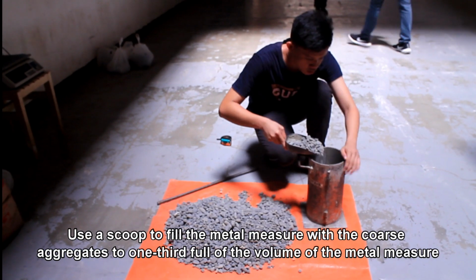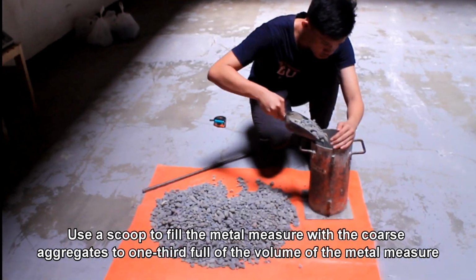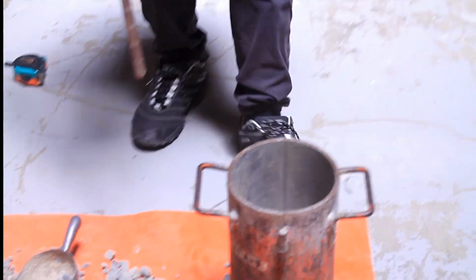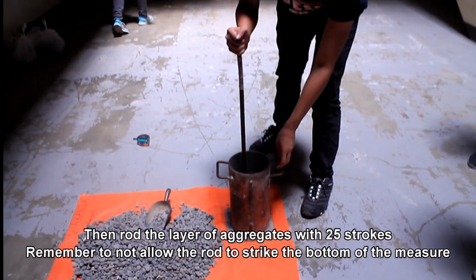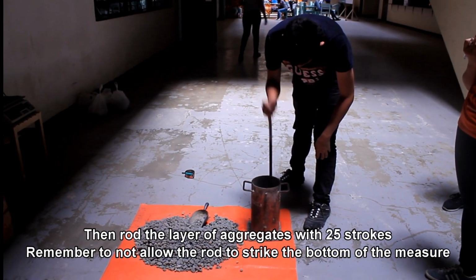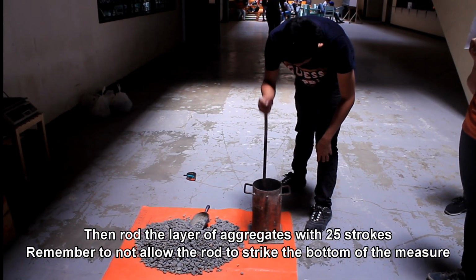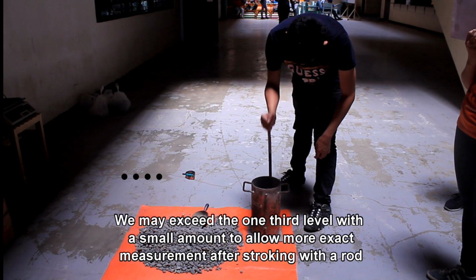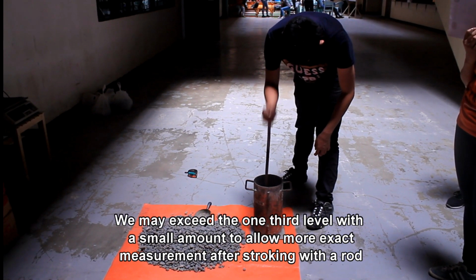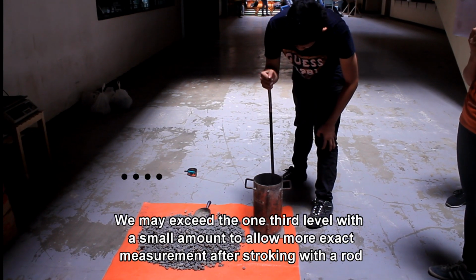Use a scoop to fill the metal measure with the coarse aggregates to 1/3 full of the volume of the metal measure. Then, rod the layer of aggregates with 25 strokes. Remember to not allow the rod to strike the bottom of the measure. We may exceed the 1/3 level with a small amount to allow more exact measurement after stroking with the rod.